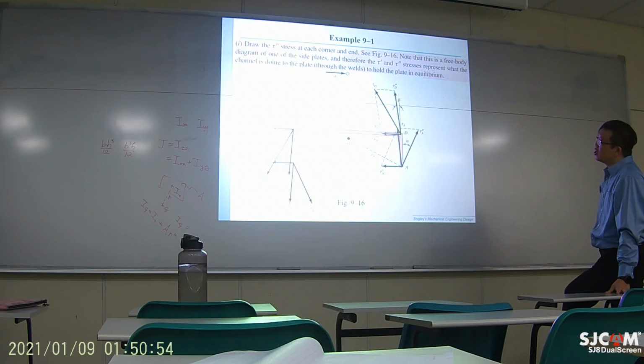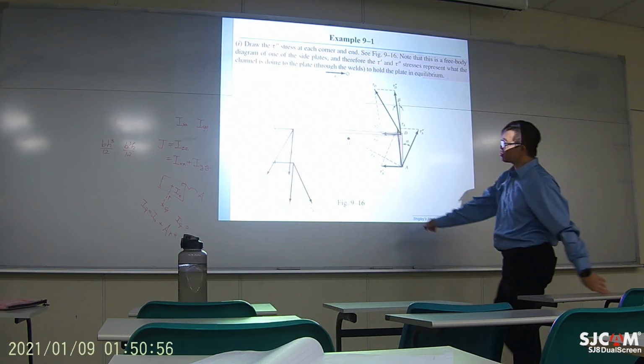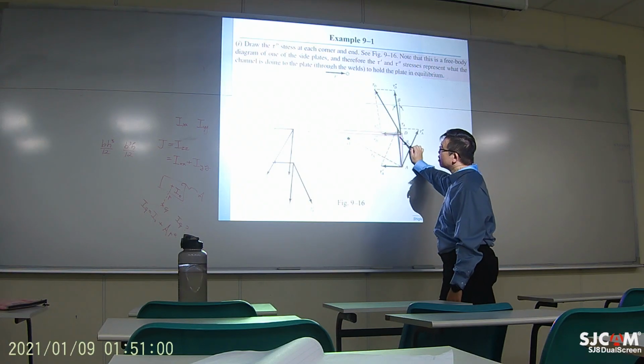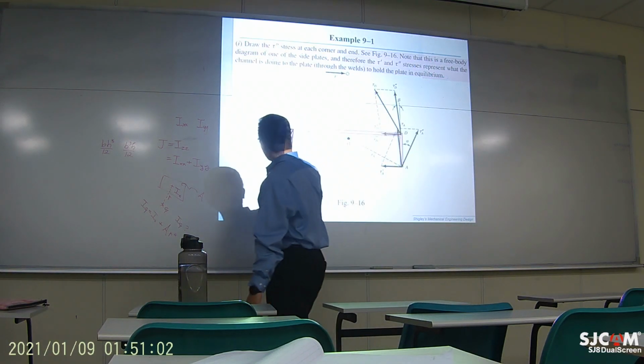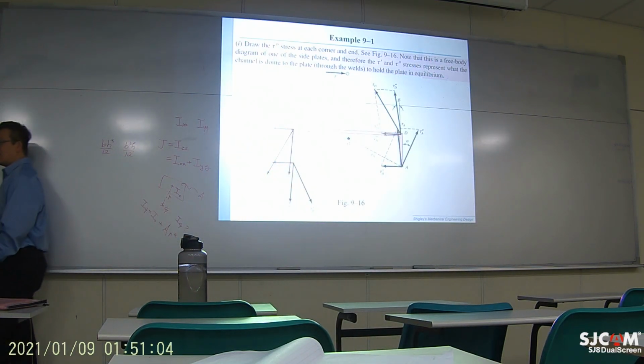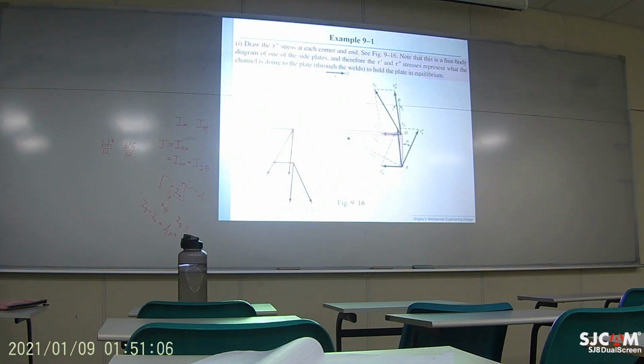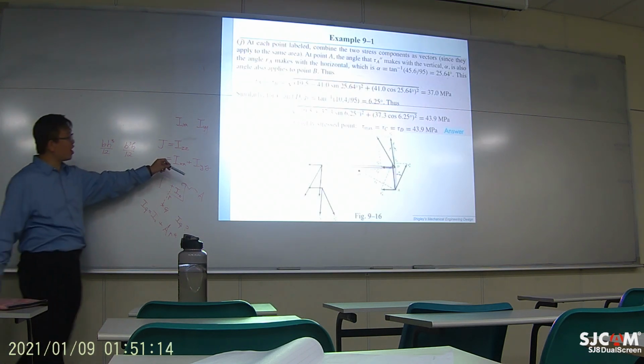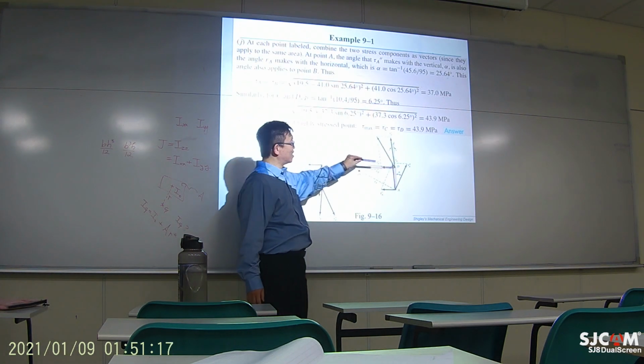And then, so at 4 different points, their stress conditions become very different. And then from here, you can see C and D points probably would have a longer vector of the total shear stress. Probably. You need to recompute it. So, most highly stressed points, C and D.